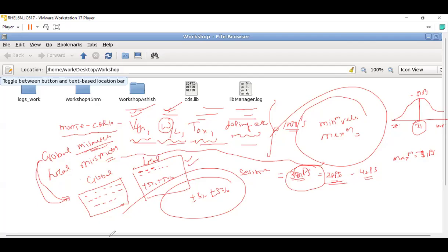In Monte Carlo simulation, you have process corner analysis, temperature analysis, voltage analysis, VTH analysis, width and length variation, oxide thickness variation, doping concentration variation, all sorts of variations you do. That is why, when you see research papers, people do 5,000 point simulation, 10,000 point simulation. The more points you take, the more accurate your results will be. And that's how you do the Monte Carlo simulation.